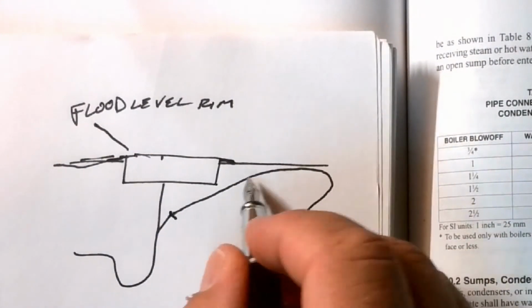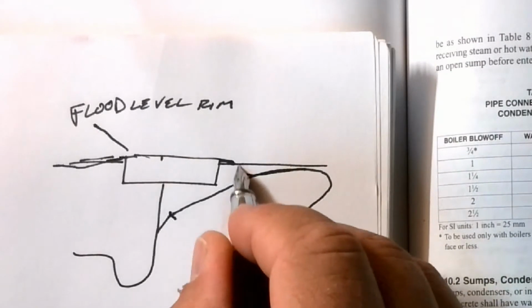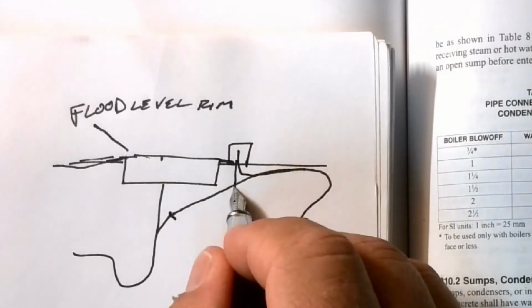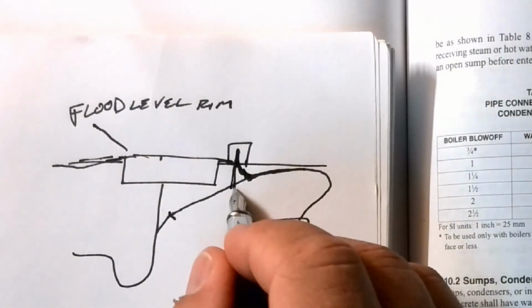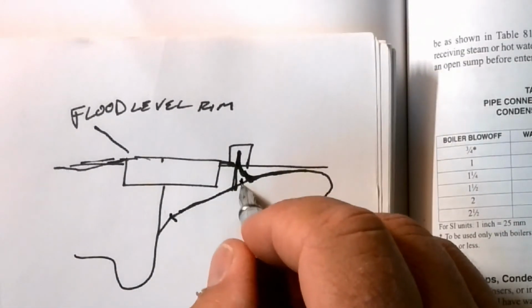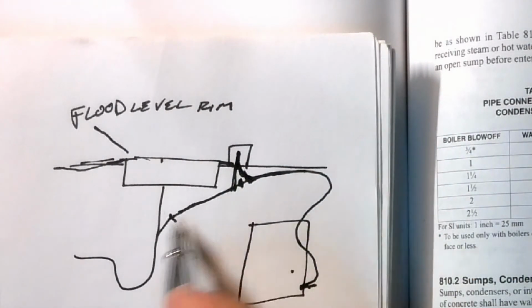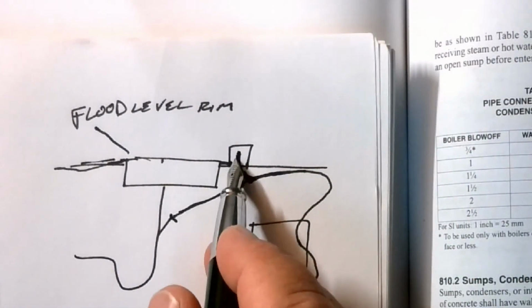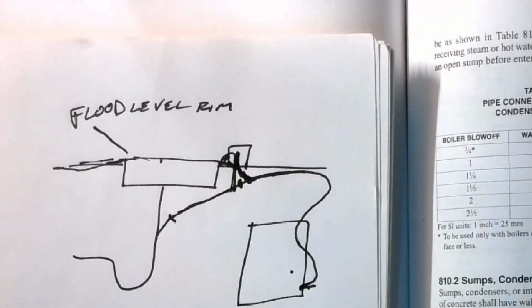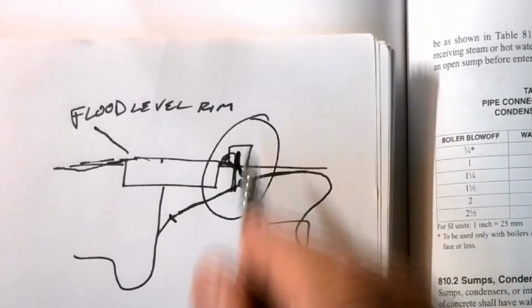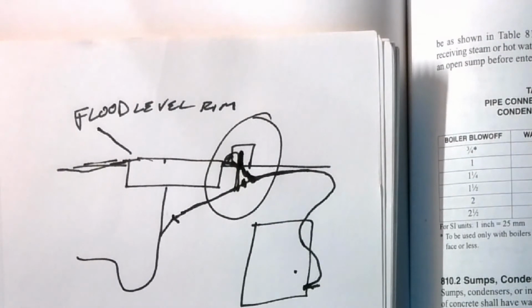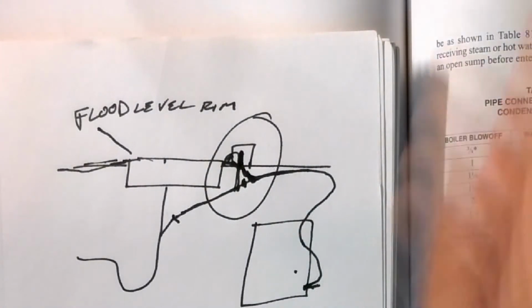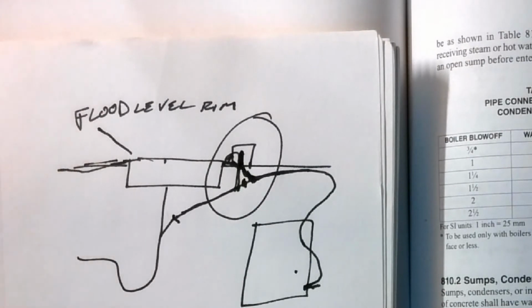So, to alleviate that, you go ahead and you put in an air gap. So now this comes up, comes down, ties in. This isn't here, right? Now, if there is a sewage backup, it's going to hit this point here and it's going to overflow and spill out. And it's not going to go in here. This is the reason. That's why you put it in. And I'm telling you, if you get into service and repair and somebody needs one and they say they don't, bring it up and say, well, this is why we use it and this is the purpose.